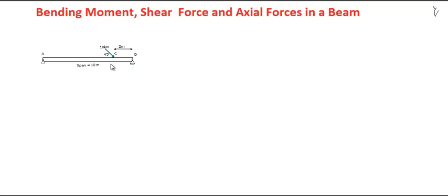How do you think the load at C is transmitted to support A and support D? Of course, the external load has to be somehow transferred to the beam section and eventually reach A and D with appropriate shares depending on the position of the load. We call those appropriate shares of the load at the supports the reactions. So this will be Dy and the reaction Ay.